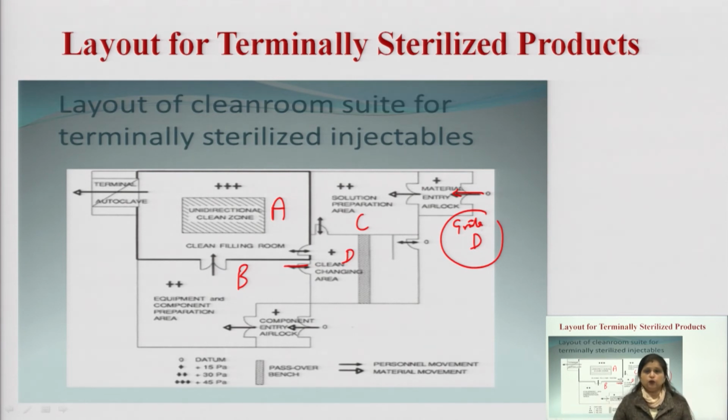What we need to do is first go to the microbial lab. In the microbial lab, you have to clean your hands and put on new lab coats. When you move from D class, which is a highly contaminated area, you have to move to the C grade. In C grade you have to change your lab coats, change your shoes, and clean your hands.